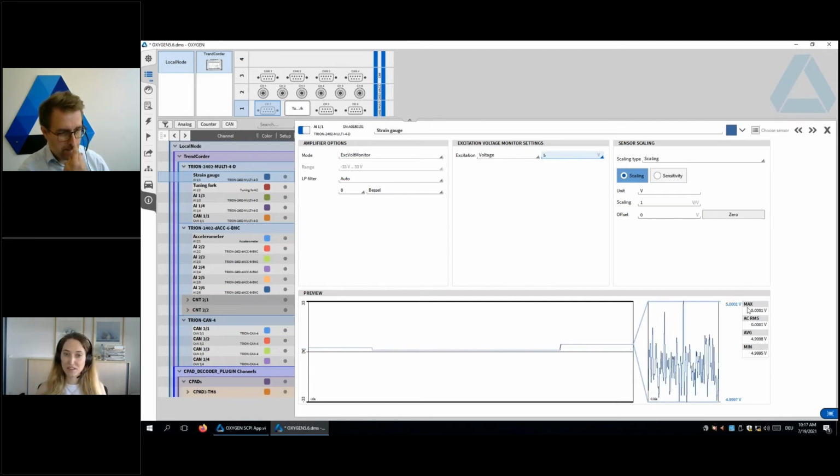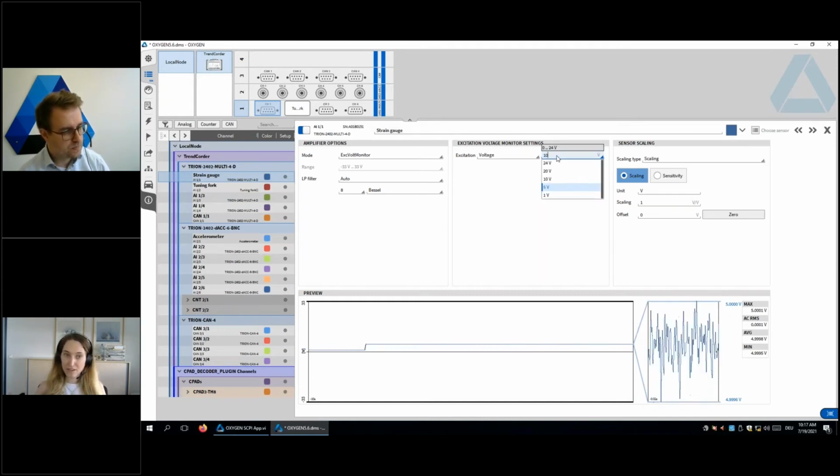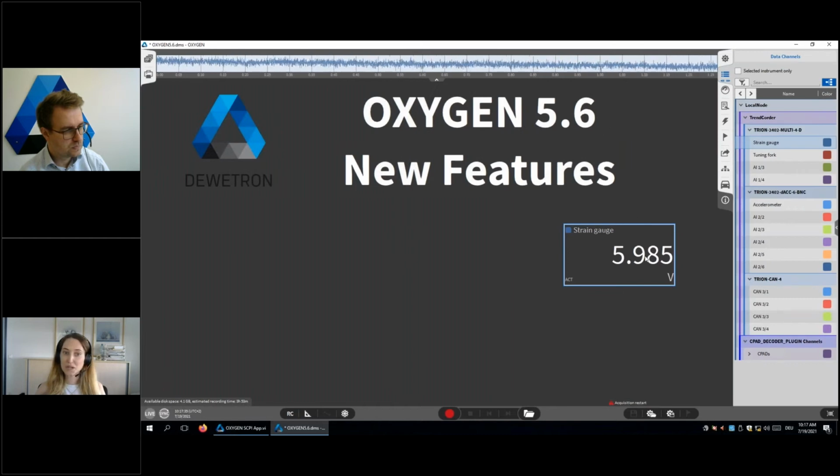And we can see down here, we can measure it back, so the sensor can be supplied. If I set it higher and we cannot measure it back correctly, so it's only almost 6 volts, the maximum power supply is exceeded, and we cannot sufficiently supply the sensor.